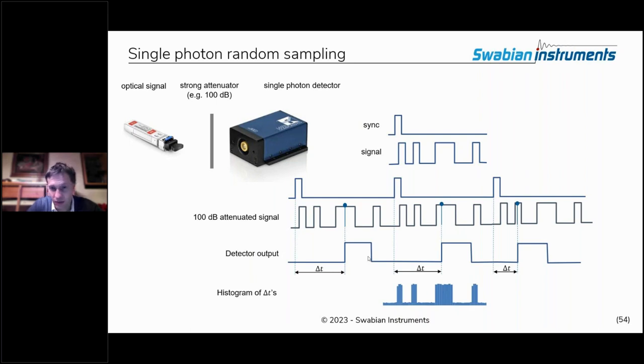You bring it down from somewhere in the milliwatt optical power range to a femtowatt optical power or below, such that only a few photons are left, and you can start detecting these signals with a single photon detector. So you bring the signal average power from milliwatt down to something like 1 million photon counts per second. Okay, and then you repeat. You shoot out this bit pattern in a repeated fashion.